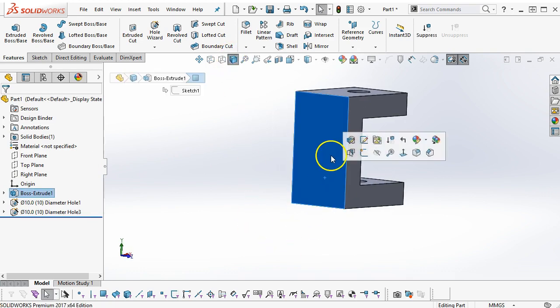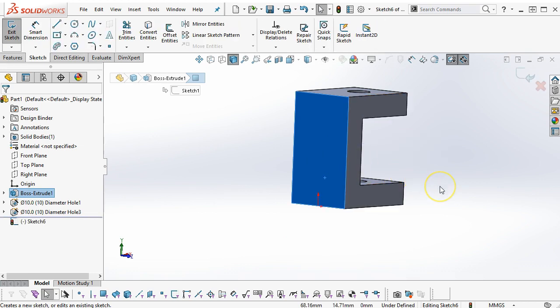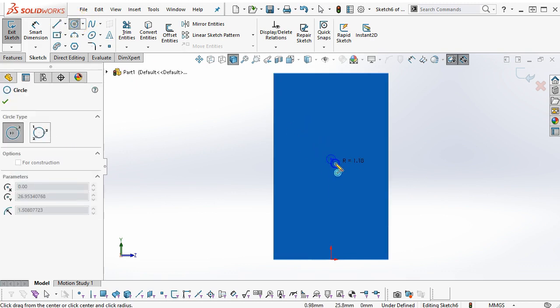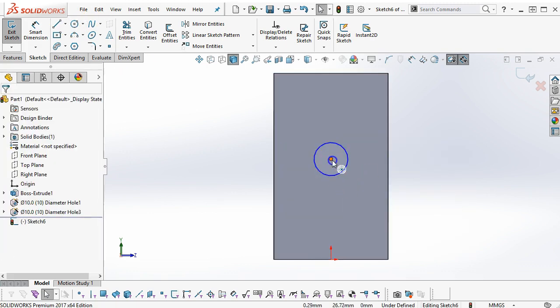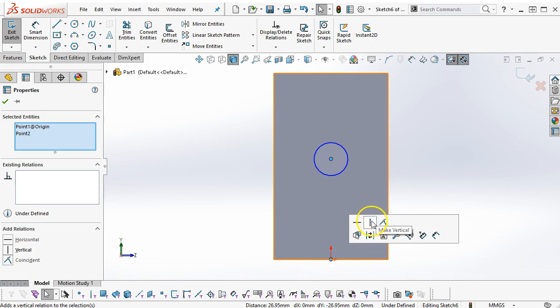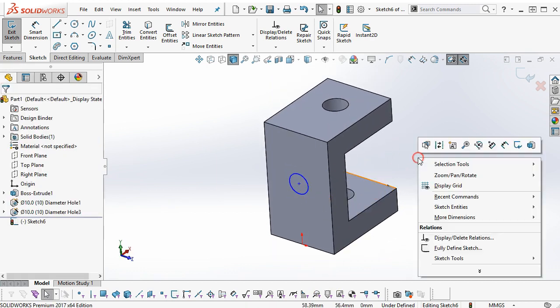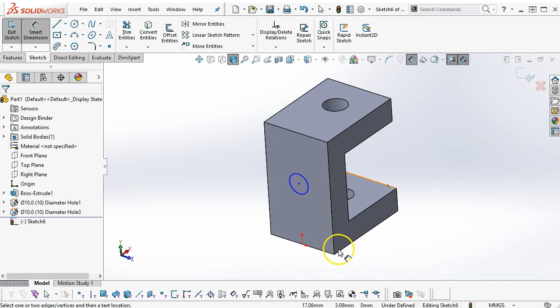All right, so those are in contrast to opening up a sketch, clicking on the face, and going to the sketch icon. I'll Control 8 to get normal to it. And we'll set vertical. All right, so I'm using the origin, so I've made a decision that since I am mid-plane, this is going to stay mid-plane.